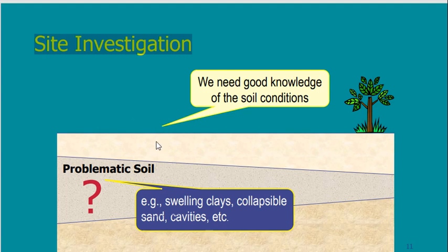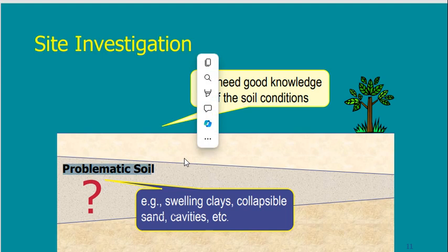I have to drill and go to this depth, take samples in a special way, and send the sample to the lab or do the testing on site to assess the type of soil. Not all problematic soils are the same. There are many problematic soils, and how problematic, I don't know. I will know if I do a good site investigation.